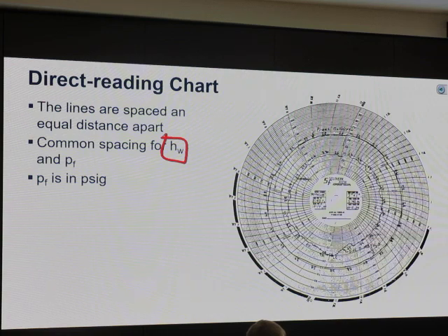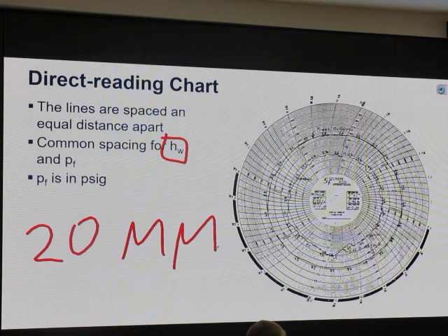So the next question: I know the flow rate. My flow rate is 20 million standard cubic feet per day. What size of orifice plate should I select? This is not as easy as when I tell you the pressure drop. If I tell you P sub F and HW, you open the table, get C prime and calculate the flow rate.